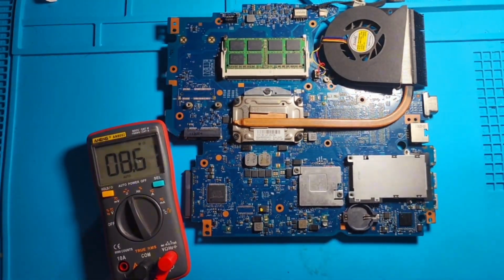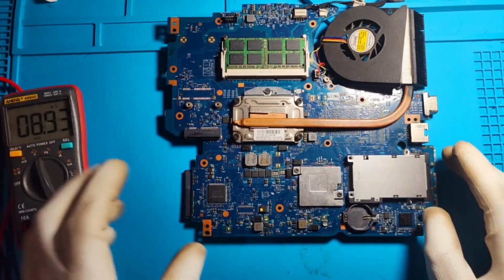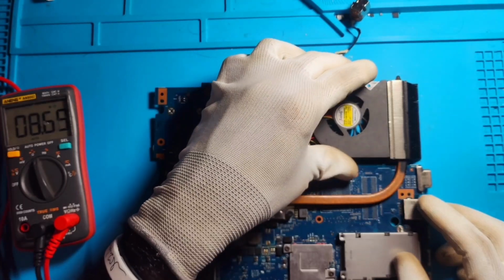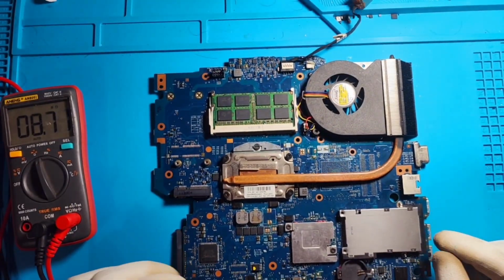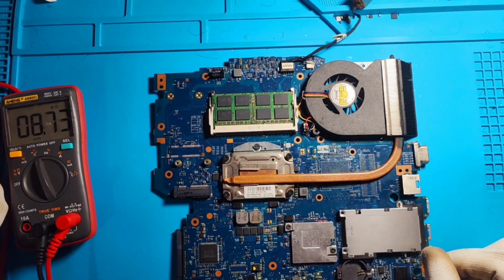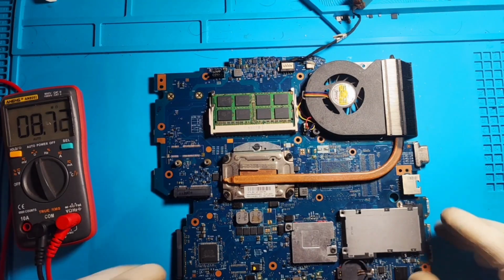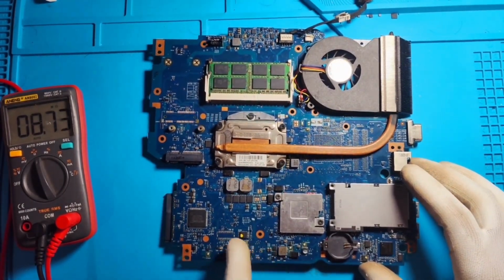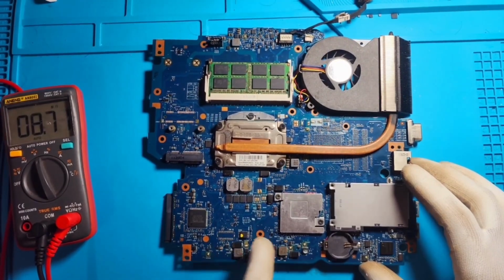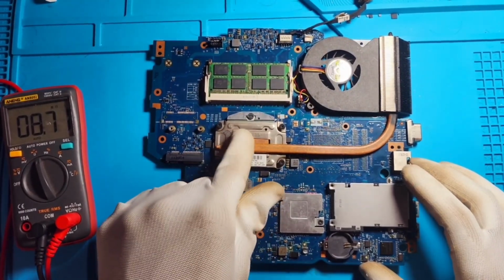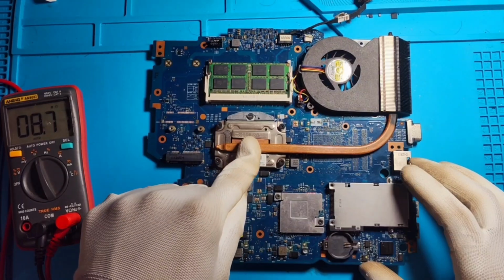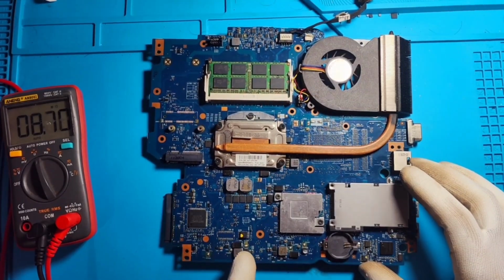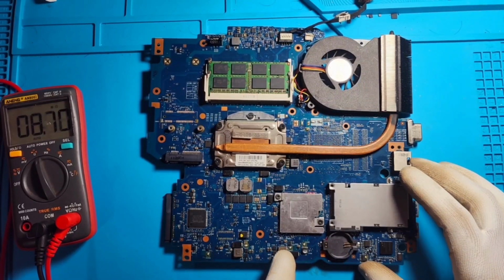I think I can go straight to the oscilloscope checkups rather than just checking the voltage, because up to the CPU core voltage I'm getting, so there won't be any problem with the 5 volt and 3 volt power supply here. The standby supply should be generated in order to get the CPU power supply. So I guess this should be present when I plug in the adapter.